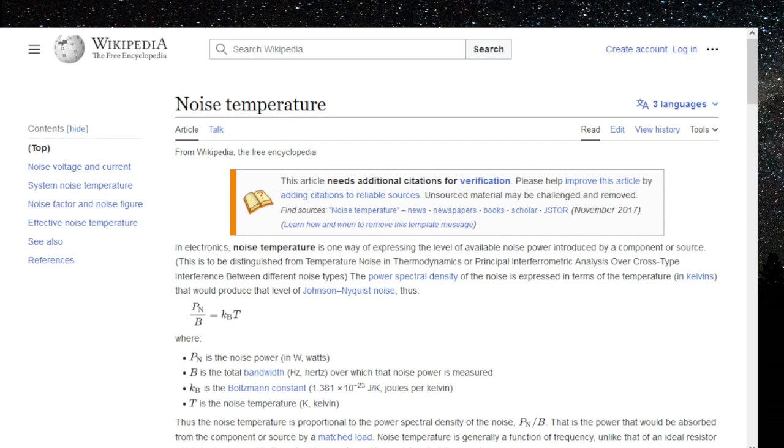It has a 50 ohm output, both high and low. When I match it into the attenuator, which is also 50 ohms, I don't think there's a problem. There's a little bit of attenuation change, but anyway, it's a 30 dB drop from, actually that's 2 volts peak to peak.